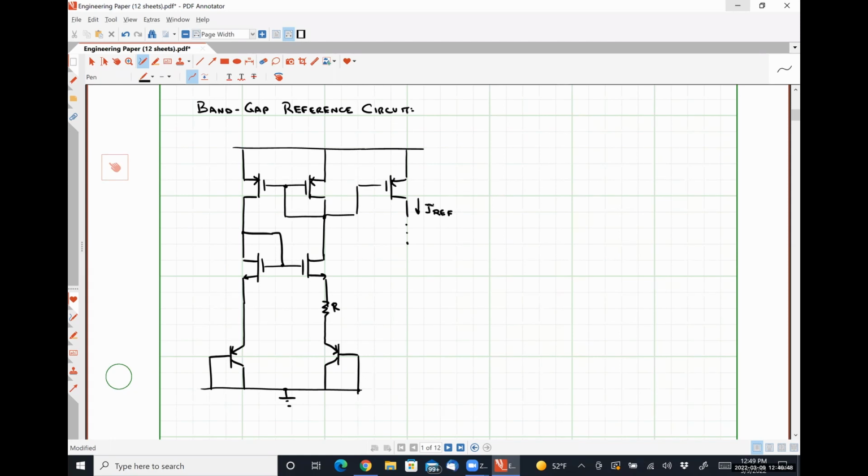Okay? So this circuit is capable of providing extraordinarily stable values of current to whatever it is connected to. There are a couple of limitations in as much as it has multiple stable states, so we actually have to include what's called a startup circuit to make sure that the state it's stable in isn't everything is off, which is a possibility, but that's a topic for 438 if you choose to suffer through that with me next one. All right, so